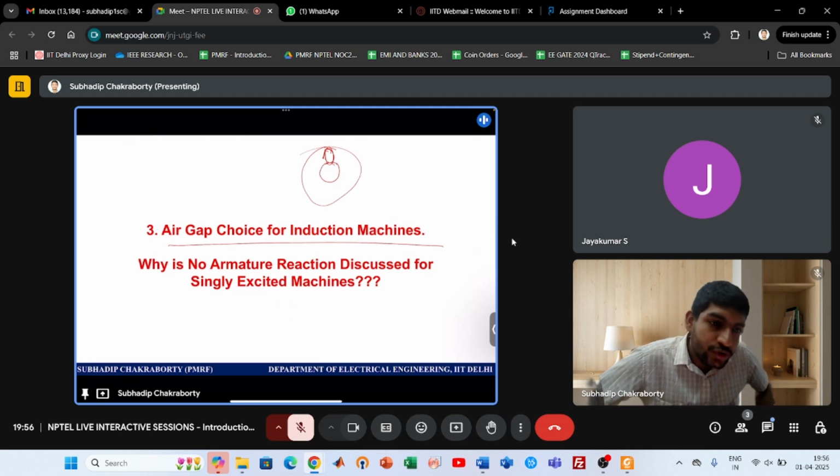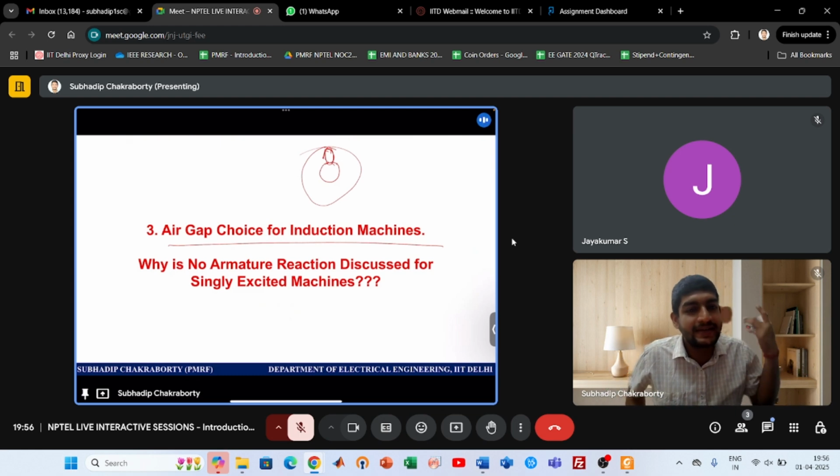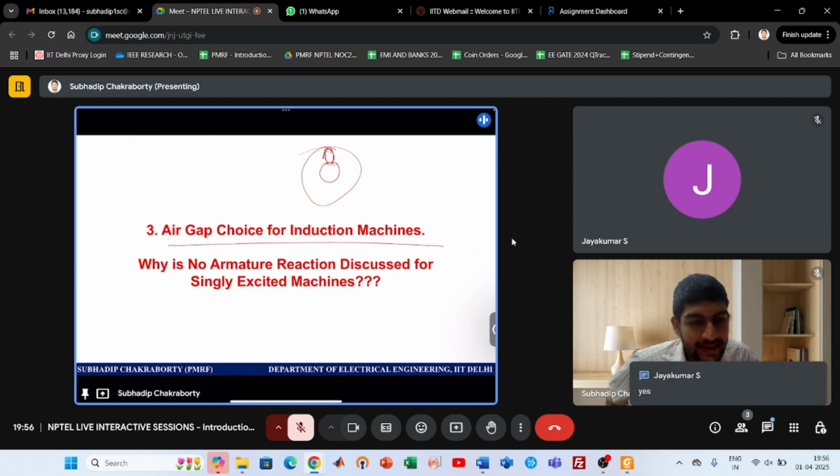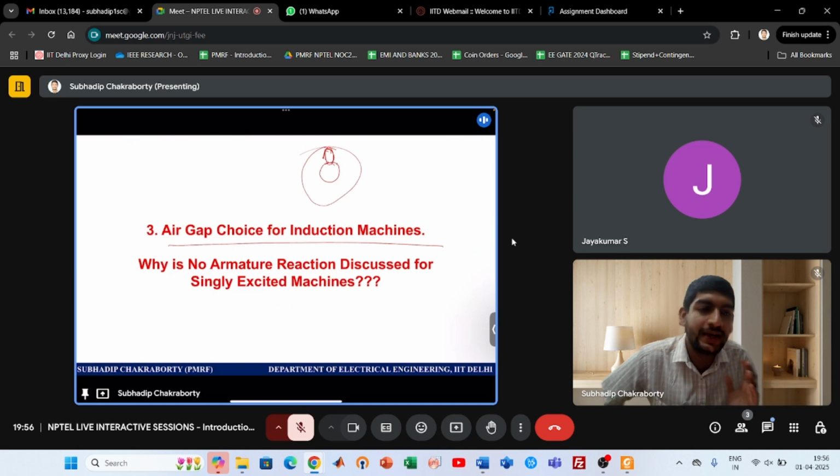But it also has to go through air to link the rotor conductor. Without linking, the coupling will not happen and electromechanical energy conversion can never happen. So it has to go through the air gap, and we say the coupling energy is completely exchanged through the air gap. Therefore, the air gap has that energy or that power.